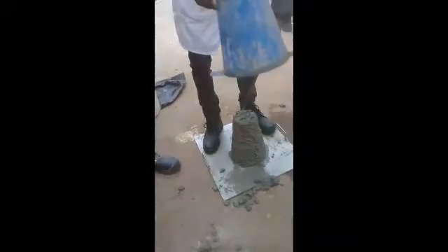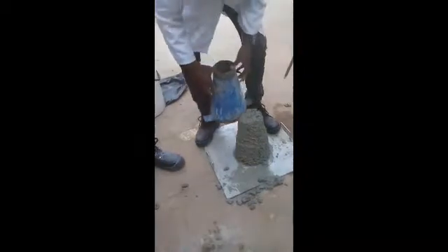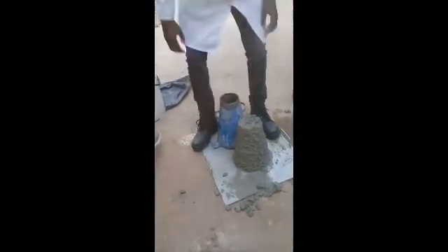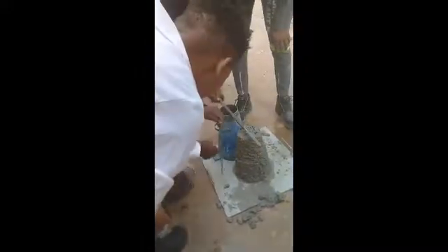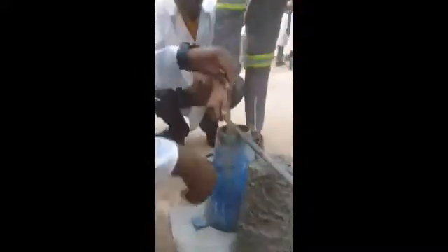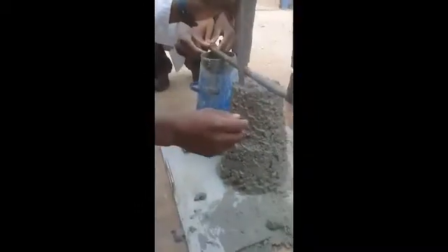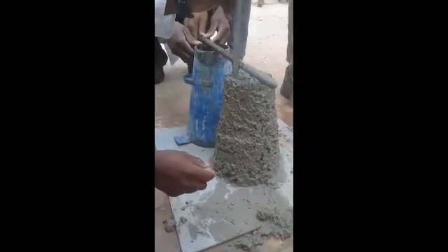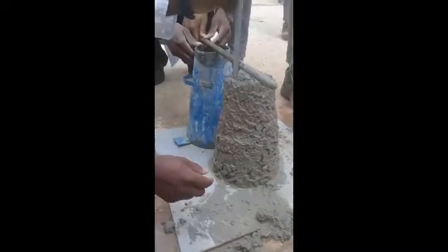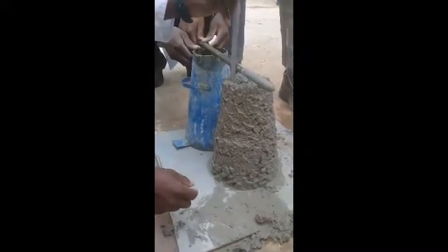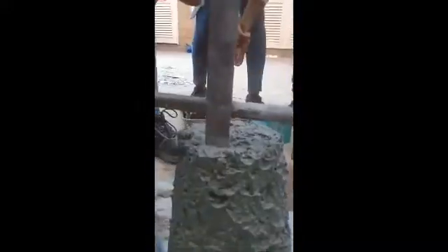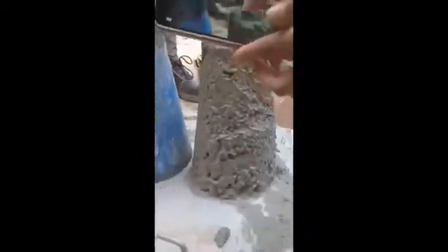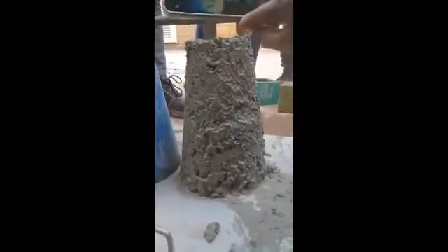The concrete subsided, and this subsidence is known as slump. It is measured to the nearest 5 mm if the slump is less than 100 mm, but to the nearest 10 mm if the slump is greater than 100 mm. The measurement from the top of the slump to where the rod is was measured to be 30 mm. With the cone having a height of 100 mm, this means that the height of the slump is 70 mm.